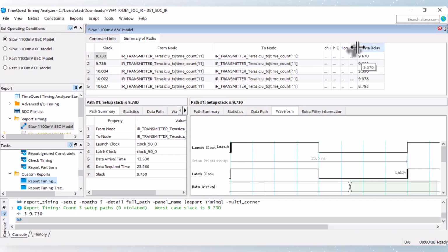Actually, we can notice that when we change the location of the lookup tables on the FPGA, the delay has increased from 5.6 nanoseconds to 9.6 nanoseconds, down approximately to 8.7. That means we have added so much delay because the wires are so long.